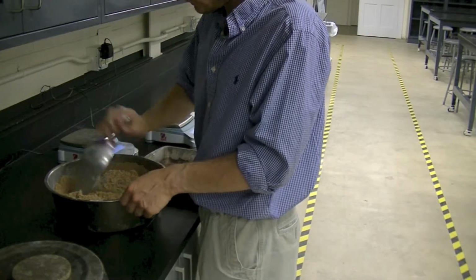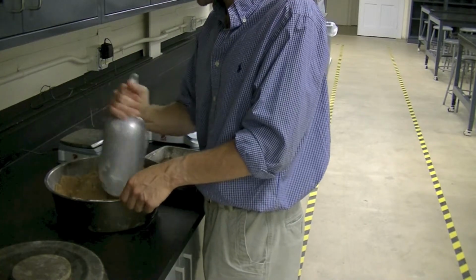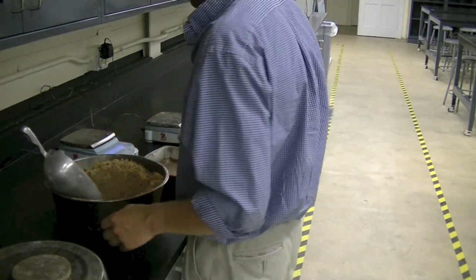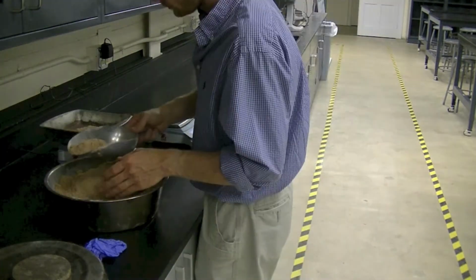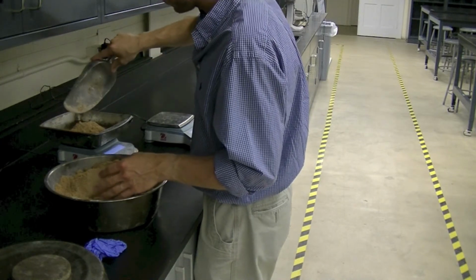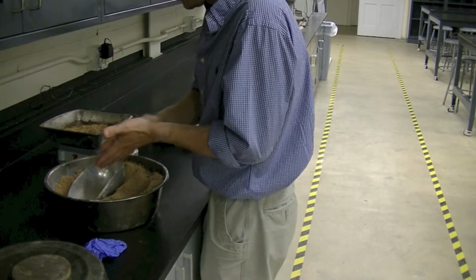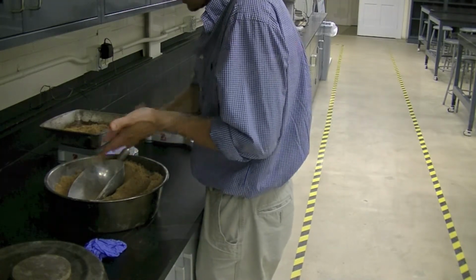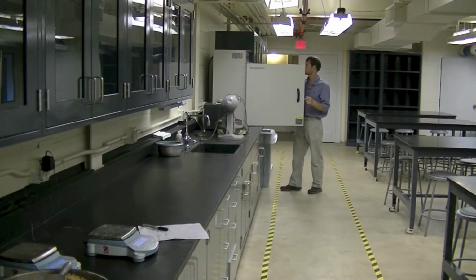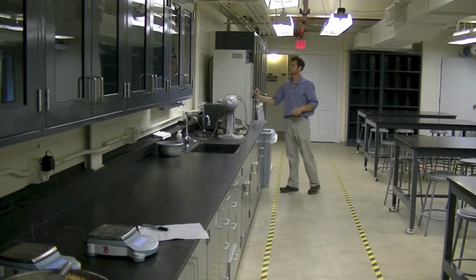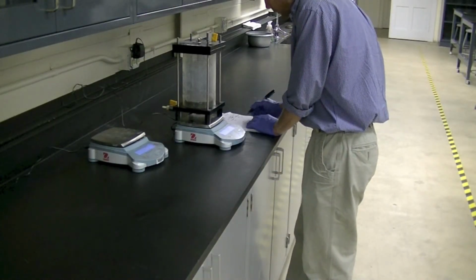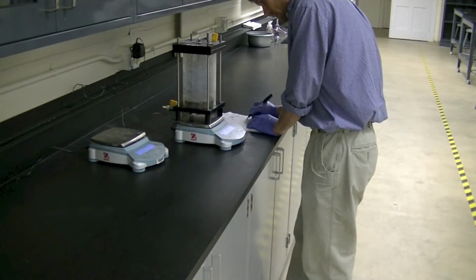In compacting a sample into the permeameter, we will use a premixed and moisturized fine-grained sample. This sample will be utilized during the falling head test. First, retrieve a representative moisture content sample of the specimen. Oven dry the sample at 110 degrees Celsius. The moisture content will later be used to calculate the dry density and finally the relative density of the compacted